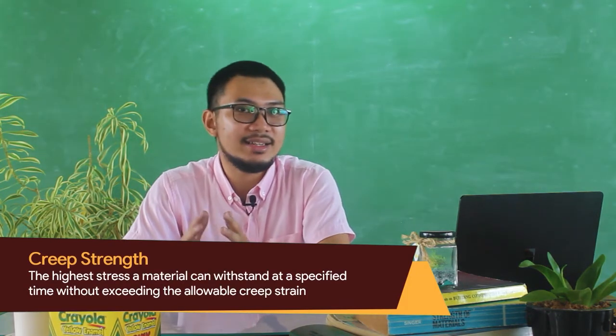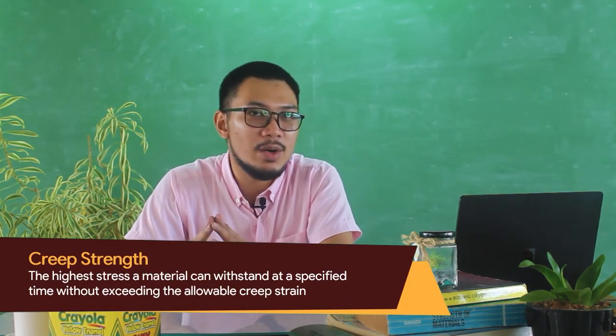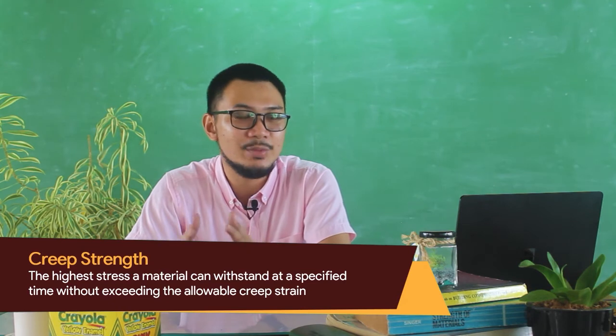Okay? That is your creep. And an important property of materials that are subjected to creep is what you call the creep strength. And it represents the maximum allowable stress that a material can withstand without exceeding an allowable creep strain. Okay?